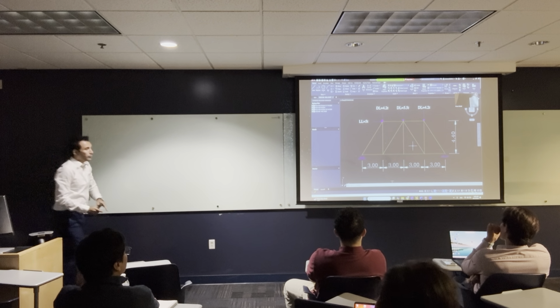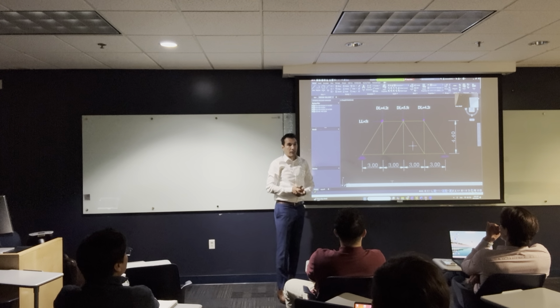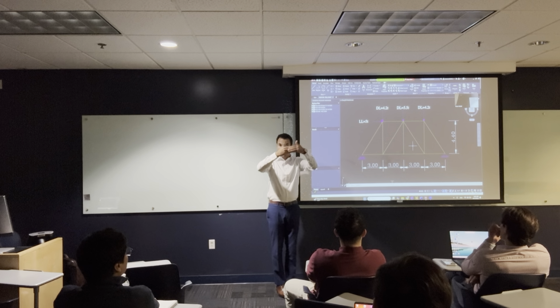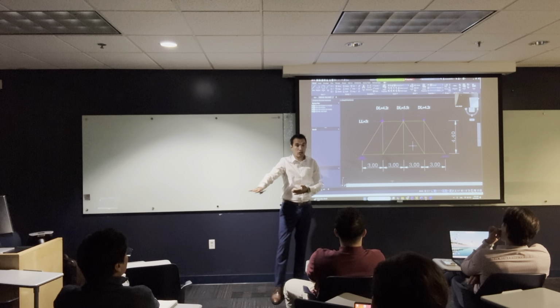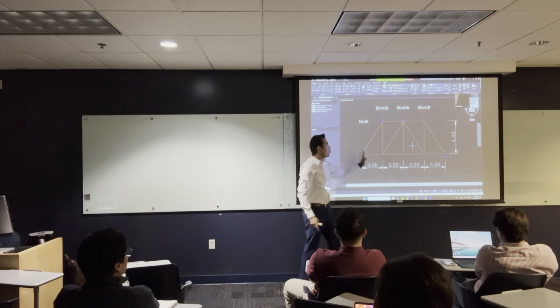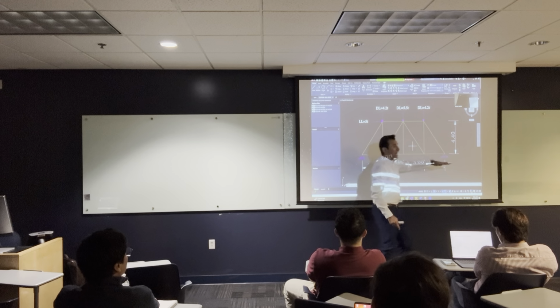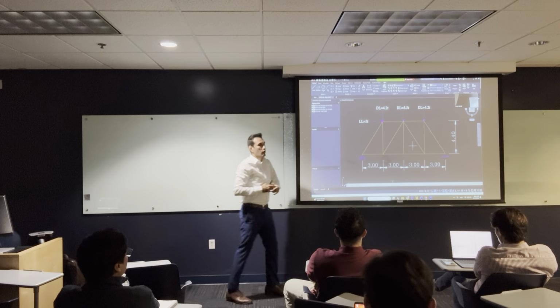Let me ask you, is this structure an XY or an XZ? XZ, that truss is going up there, like this, not a planar structure in the XY direction. So tell me, how many grids do I need in the X direction, and how many grids do I need in the Y direction to start drawing this structure? Can you tell me?